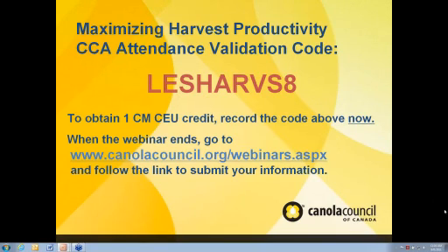Obviously, slowing down is going to help, because if you're running on the flat where it's pretty much met its efficient range, that efficiency is going to drop off on the side hill, and you're going to have to back off on feed rate.